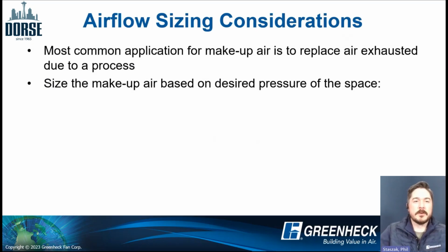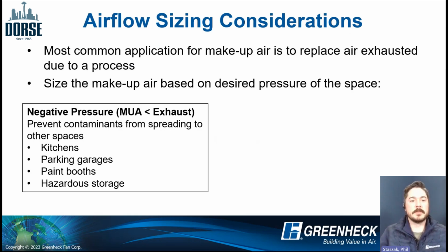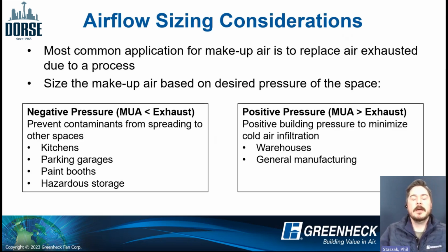Okay, so airflow considerations. Most applications, as I explained earlier, are more of a one for one. So we're exhausting X CFM, therefore we need to bring in X CFM to roughly balance out that airflow. Slight negative, slight positive in some cases. Where you want a slight negative: kitchens, parking garages, paint booths, hazardous storage, wastewater treatment plants, things like that.